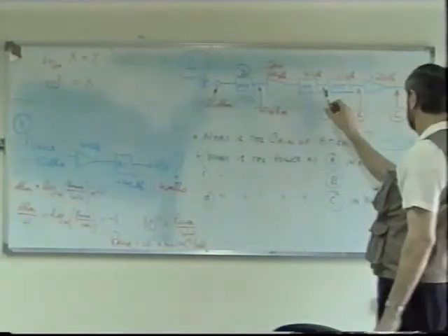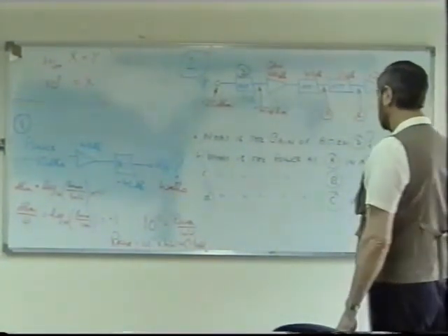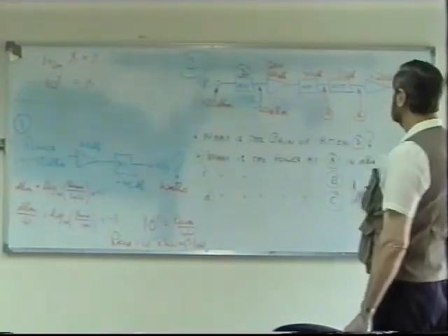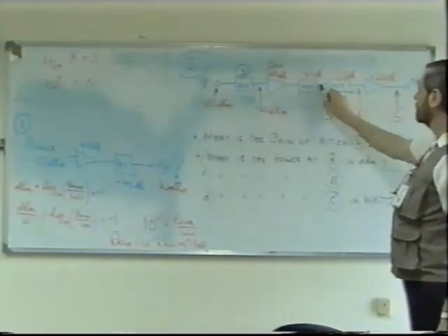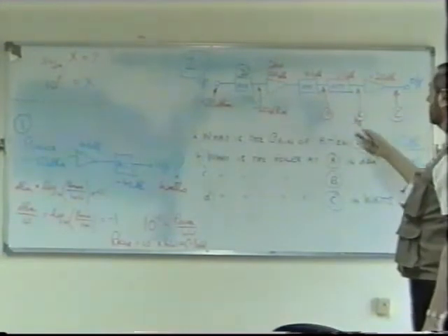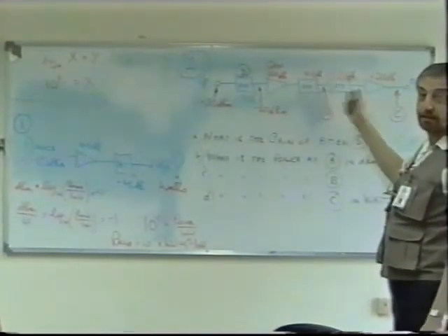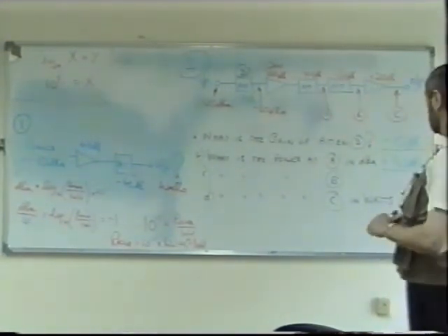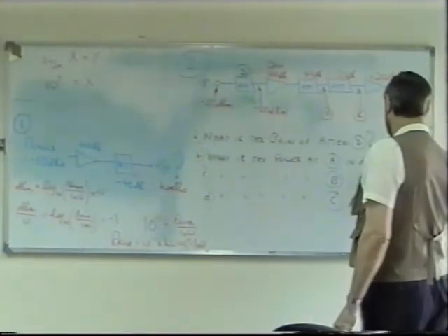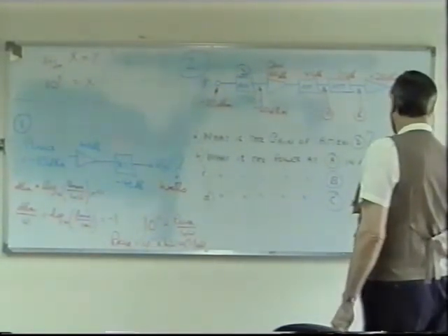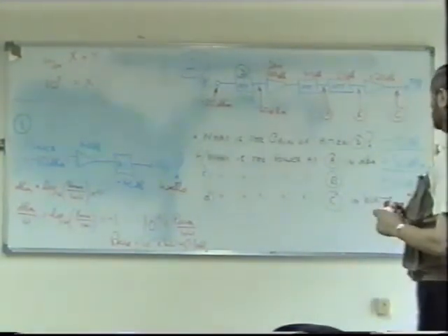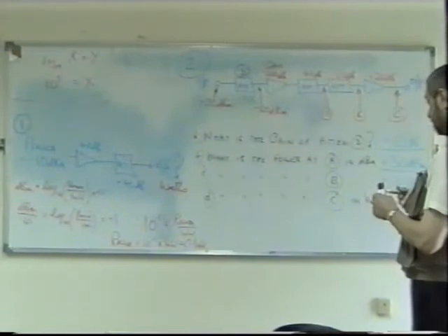Now we have the power at A, and what is going to be the power at B? Well, it's quite straightforward now. We've got plus 30, minus 20, 10. That's right. Don't forget it's still plus at the moment, plus 10 dBm. So that's here.